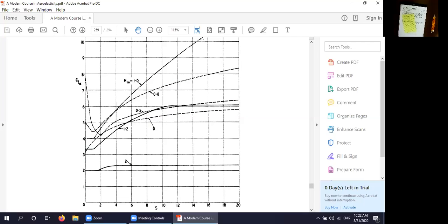So this two-dimensional supersonic theory is breaking down at large time as you go to the steady flow limit. Remember, physically, what we're doing is we're thinking of this airfoil will be given either a step change in angle of attack to a constant value, or a step change in downwash, dH/dt divided by U infinity. And at large time, at Mach number 1, you never reach a steady flow condition. It blows up, which is an indication that the theory is breaking down.